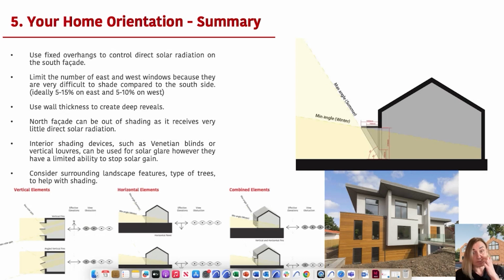The G value is the factor that can help with managing that overheating, but it can have an impact on cost. So if you ask the supplier to provide your window with a lower G value, it can have an impact on costing and aesthetic, and generally is not an economic solution and would be the last recommended resort.